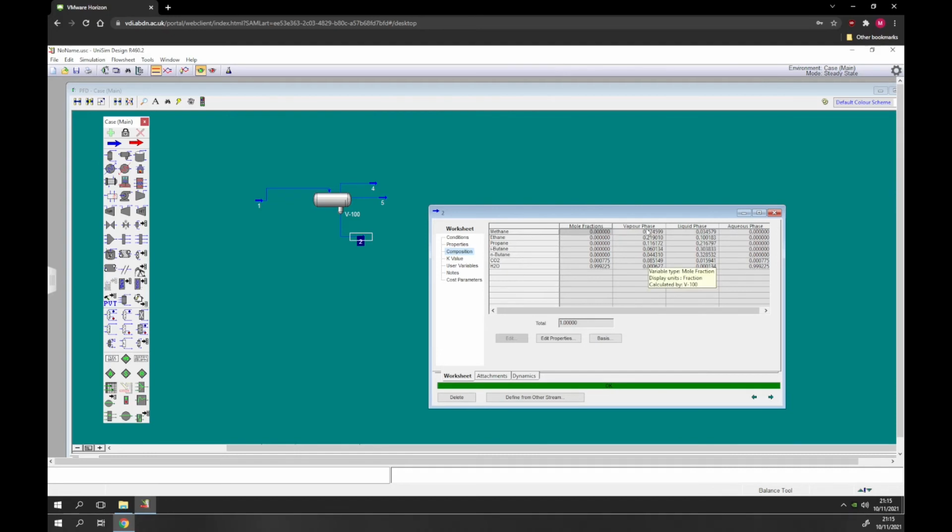You'll notice that these vapor phases have a composition, which is oil and gas, and so does the liquid, and that's a bit confusing when it's 0 here, but then these phases have it, and it's because those phases don't exist. So if I change the basis to mass flows, what you'll notice is it's all 0, right? So there is none of that phase. So the mole fractions could be anything because there's nothing there. There's no actual flow of it. So as soon as you put it in mass flows, which is my preferred basis, you can actually see there's only this aqueous phase here, that's the special phase, the water phase, and everything's inside that.